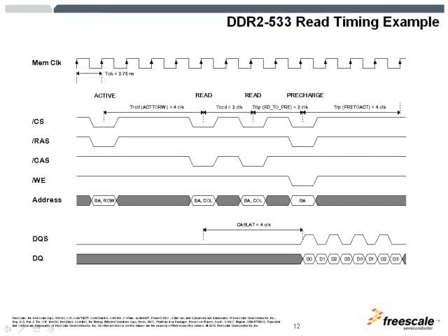From the very first read command, on the very bottom, you see the DQS and DQ signals, which is the data bus. After the CAS latency, which is 4 clock cycles here, the data starts streaming out. On the rising and falling edges of the strobe, you see that the data is flowing. You also notice that the strobe and data are edge aligned when they're sent during the read by the SDRAM.